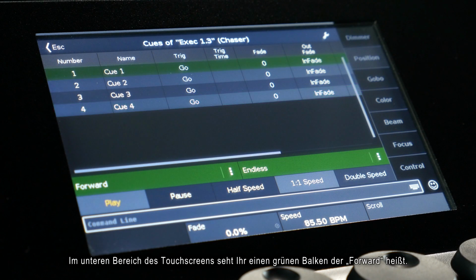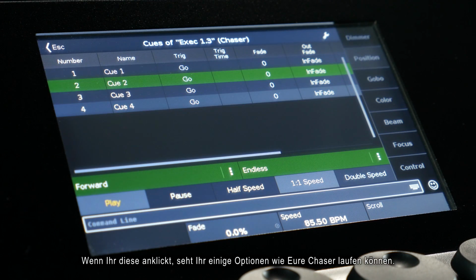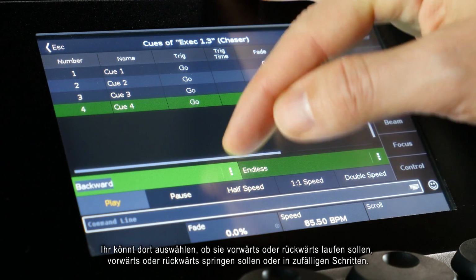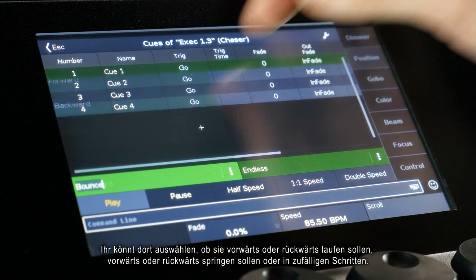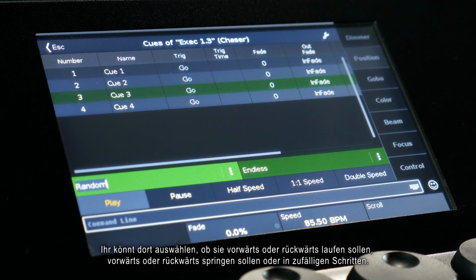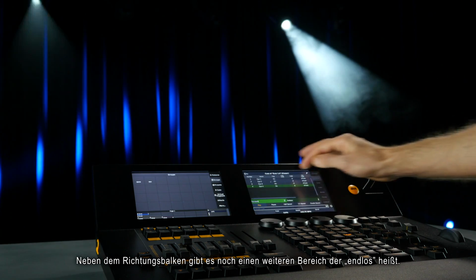On the lower part of the touchscreen, we see a green bar labeled forward. On the right of this bar are 3 dots. By pressing this, we are shown some options on how our chaser should run. We can change our chaser from running forwards to running backwards, bouncing forwards and backwards, or even running to random steps. Next to the direction bar, we have another control that says Endless.